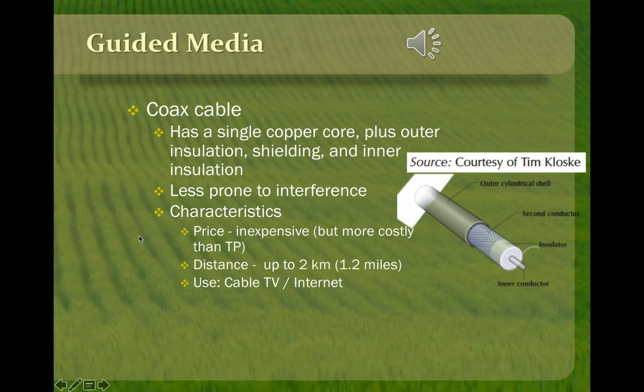Now we'll talk about coax. And really, when you got your old VCR, it probably came with a patch cable that was a piece of coax. That was RG-59. That's not as reliable. It's much more prone to interference than the RG-6 wire, which is really the cable wire that you see out on the phone lines and being directed into your house. It's what the cable companies install.